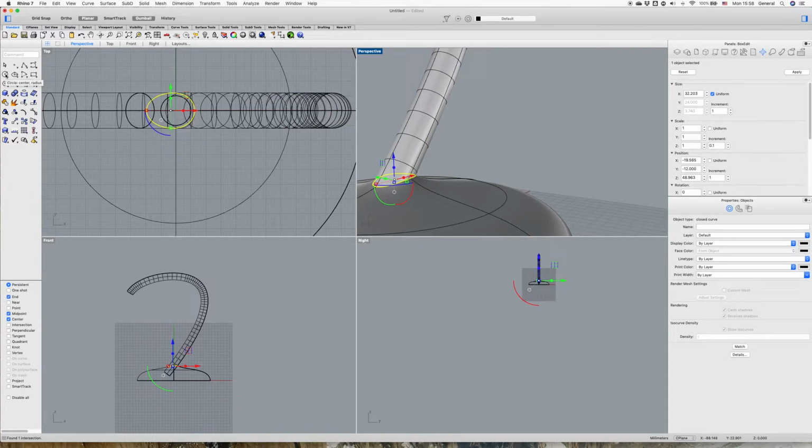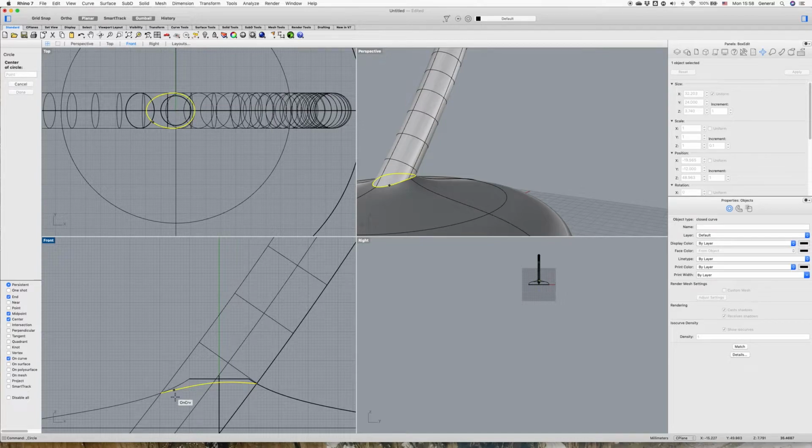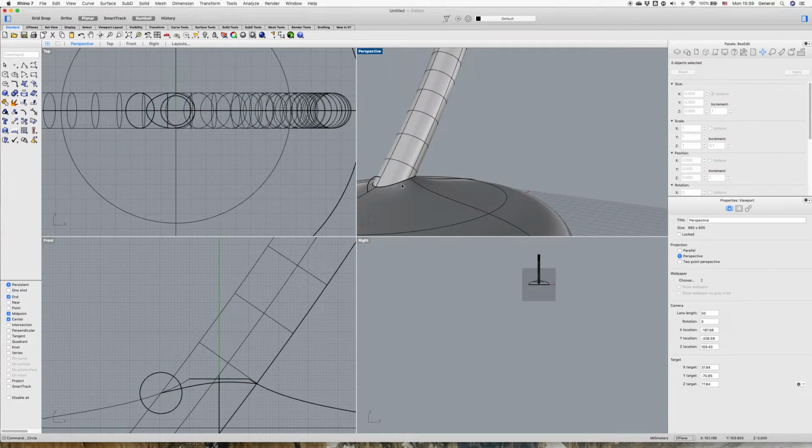And a good way to do this, we go back to our circle and we go around a curve, which we have used in the past. Can go there. Let's give this a healthy diameter here. So we have the object intersection with this circle here. And we do the same trick again. We go to our surface tool, we do another sweep. So the rail is the intersection. It's this one, not this one. We do not want to have that. Do the sweep rail again.